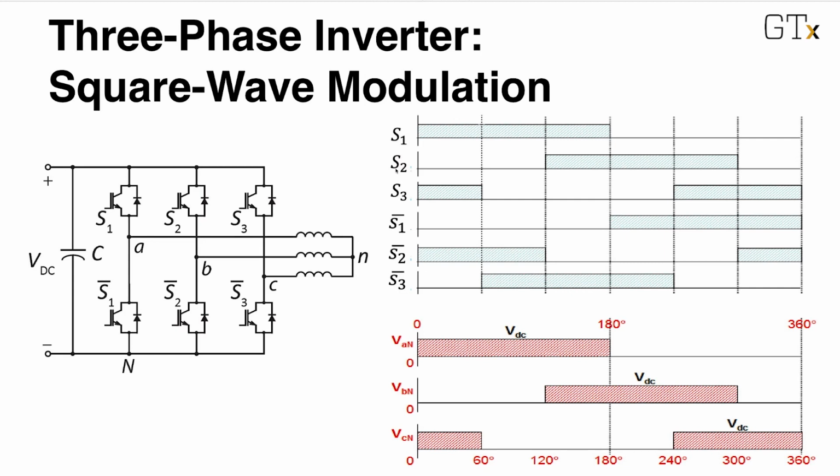However, since we would like to synthesize three-phase balanced AC side voltages, we have to introduce the phase angle displacement between the three phases. So for phase B, as you observe, we have the same switching pattern for switch S2 with an additional displacement angle, which is 120-degree phase shift with respect to the gating pulse for switch S1.